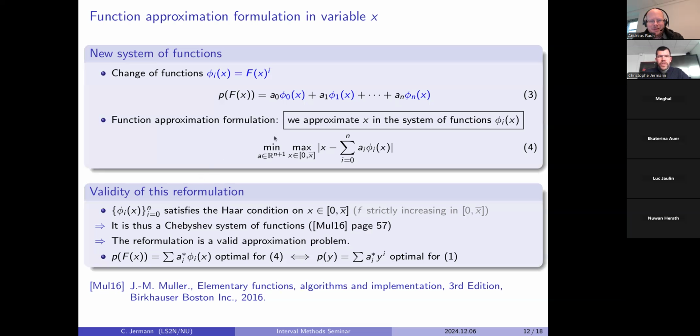Well, the thing in our context is that we are not so much interested in computing the phi at some points, but instead in computing the a's. But probably you need the same thing to obtain the exponential, isn't it? Yeah, and for that you would need to evaluate the characteristic polynomial of a matrix. And this could also become quite complicated if you have, for example, high-dimensional system models.